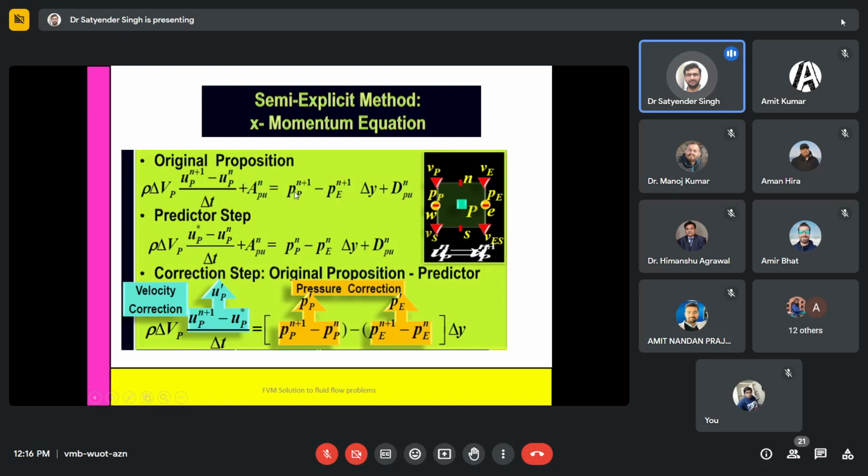If it were known to us at some level, let's say at the initial level, or at some particular boundary, then we could make a reference of it. If you are well aware of pressure as a boundary condition for a fluid flow problem, or you may be using any CFD tool, then for the boundary condition for pressure, we straightaway go to the outlet and assign pressure p equal to 0 as a boundary condition there.